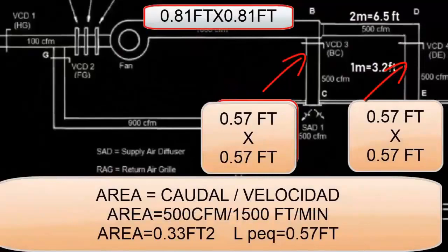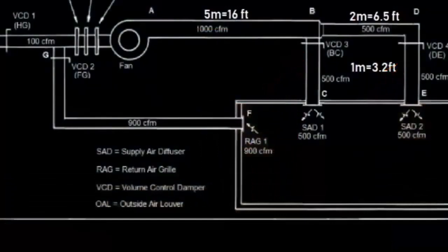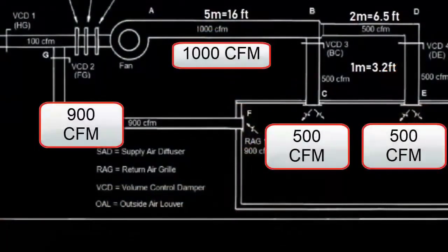We can notice how the installation has a return duct. This return handles 900 CFM. This means that of the 1000 CFM of cold air that enters the premises, 100 are sent to the street, and 900 CFM return to the machine, to be cooled again. Thus, 100 CFM of new air must be introduced, to carry out the renewal, and recover the 100 that were discarded. The renovation is carried out to maintain the environment of the premises with a low concentration of pollutants.